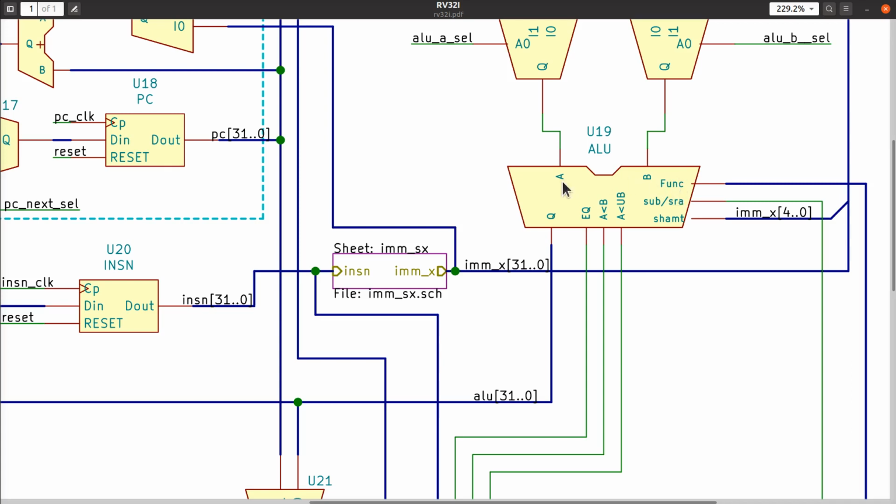So let's just assume this ALU does everything we've talked about in the past, plus it can shift, and the amount that it shifts is given by this shift amount input field here, and you may recognize that because it is one of the things that comes out of the immediate field for the shift immediate instructions. And these are the bit positions that we're concerned with for how far we need to shift. We'll talk more about that later when we look at some instructions.